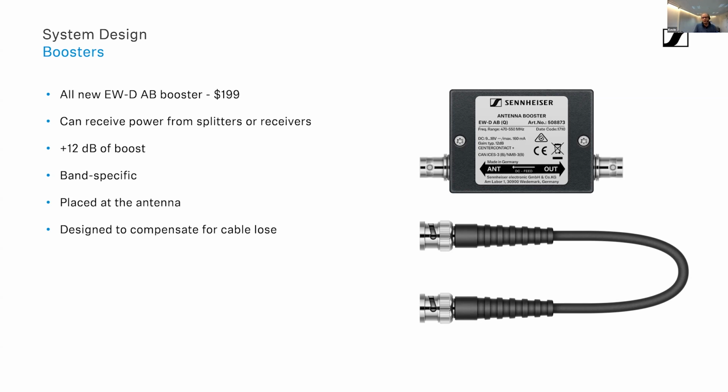Well, you do have an auto scan feature where it looks for occupied spectrum, and it will then put a frequency in there. It will do this based on the amount of channels you have connected. Currently, with the EWD and the Smart Assist app, you can have, I believe, 16 channels. So this will do a coordination or a setup for 16 channels.